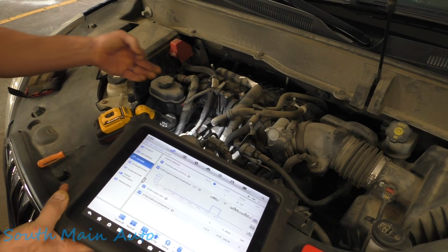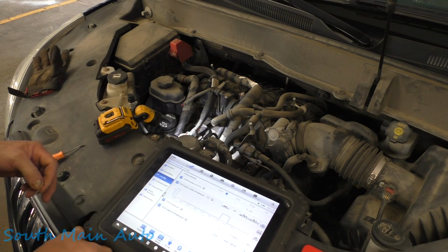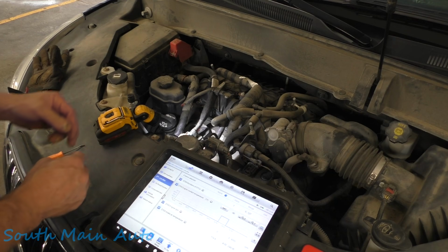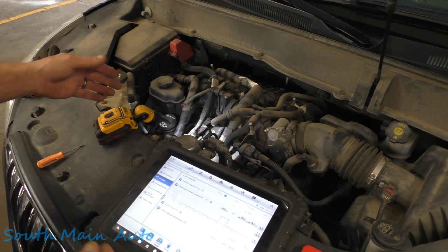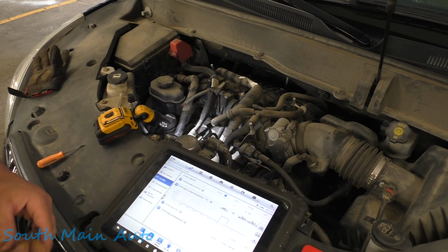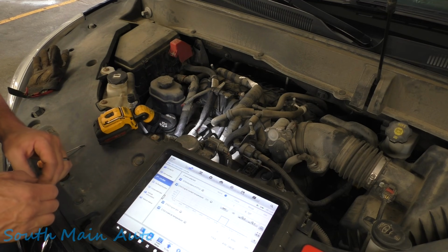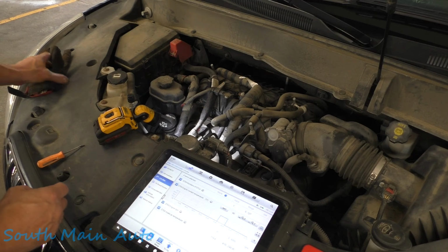So that tells us that our wiring from here to the PCM is good. The PCM can calculate, probably just through a code there. Granted, you could have a PCM that's failing and this and that. The sensor's like 20 bucks, and it only takes a minute to change. So we're just going to swap that out. We'll let it go through a warm-up cycle, and that's that. So kind of an easy one, folks.